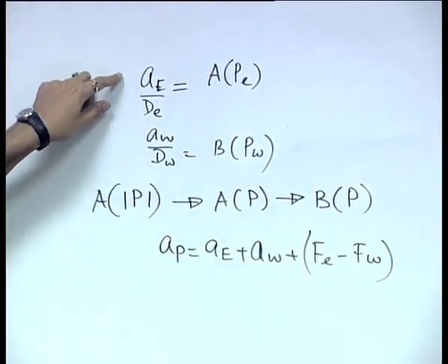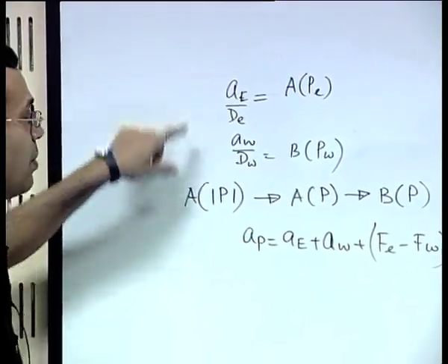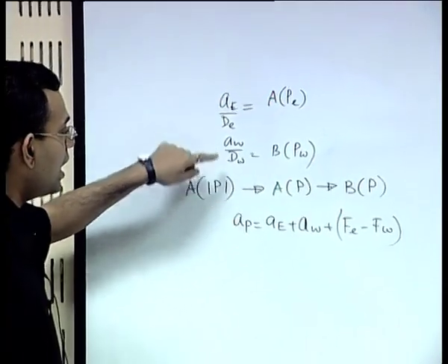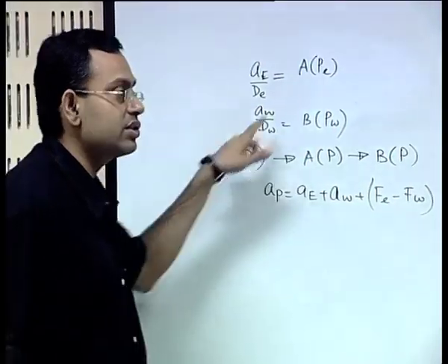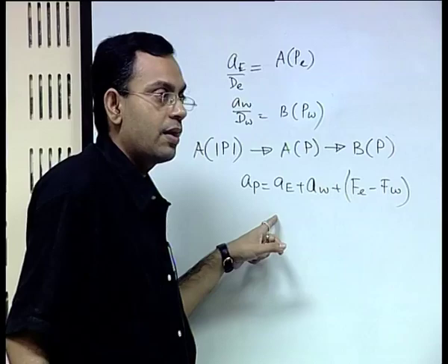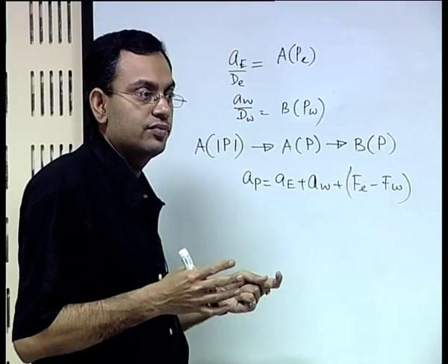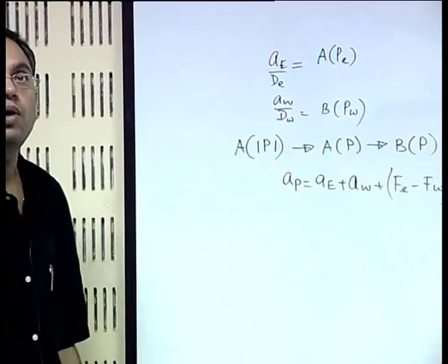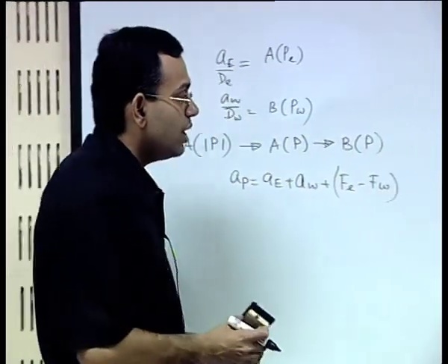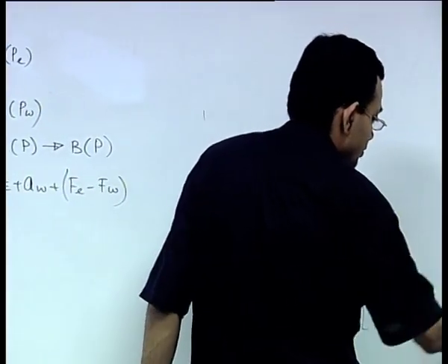So, you can calculate first the generalized coefficient, then the dimensional coefficients AE and AW, and then AP as a function of AE and AW, and that is how you can create the discretized equations. Okay. So, this is a fairly straightforward consideration for a one dimensional problem. What happens if we consider a two dimensional problem?